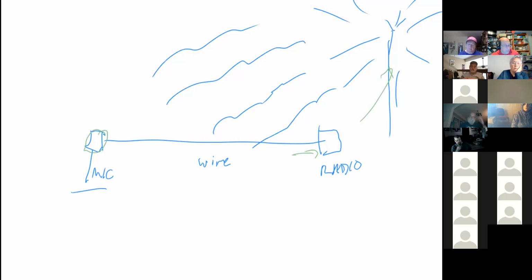So there's something that we add to this, and this is a filter. You can put a filter that would basically filter out the RF and allow just the audio to get through, and everything's better. Or we can just use shielded wire, right? Sometimes it works, but let me ask a question. What's a shield made of? Wire. Wire, that's right. So sometimes it works and sometimes it doesn't.